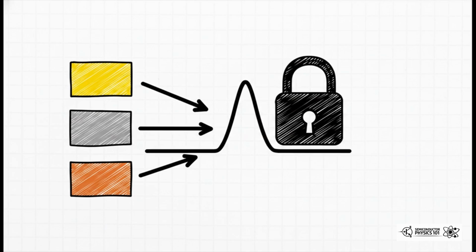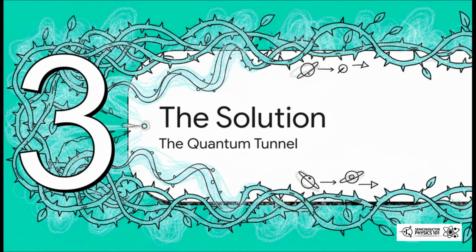Why? Because it means it almost doesn't matter what metal you use. The height of that energy barrier is now locked in, determined entirely by the semiconductor's own surface physics. We've just lost our main knob for designing the junction we want. So, if nature is so insistent on building this barrier, and a stubborn one at that, how on earth do we engineer our way around it?